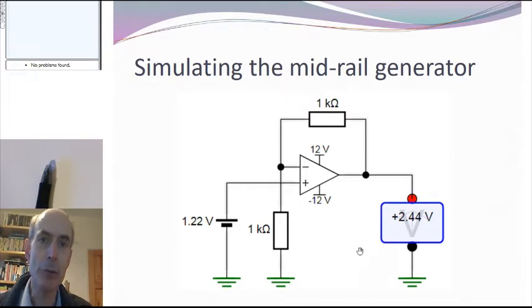What we're trying to do then is to produce a low impedance voltage source, such as the output of an op-amp, which is held at halfway between 0 and probably around 3.3 volts, the voltage of your derived power supply. That's around about 1.65 volts or so.